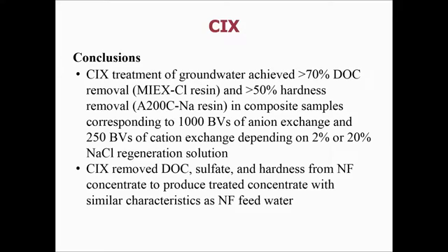And then when we're looking at these composite samples produced by the combined ion exchange process, we're seeing greater than 70% removal of DOC, 50% or more removal of hardness. I should also mention, I could talk about this separately, but these bed volumes of water treated are reasonable amounts of water that are being put through the process. And then, in the second bullet here, we can also think about applying combined ion exchange to concentrate streams, whether it's NF concentrate or maybe there are some interesting wastewater or industrial applications for combined ion exchange as well.